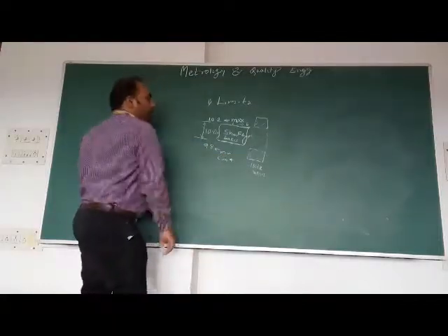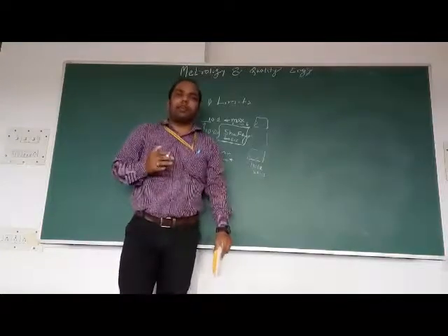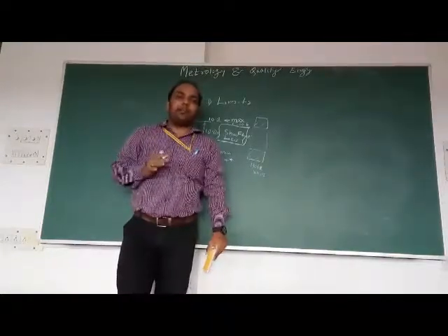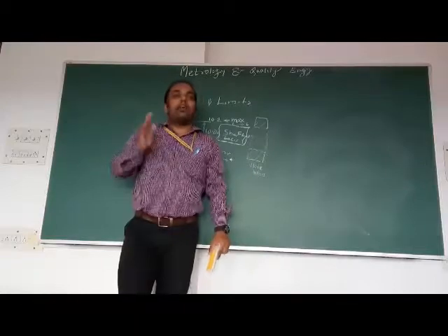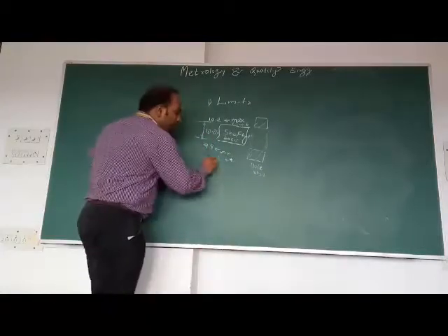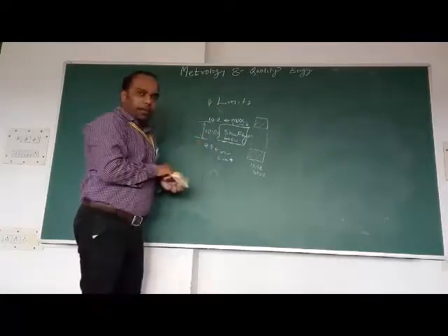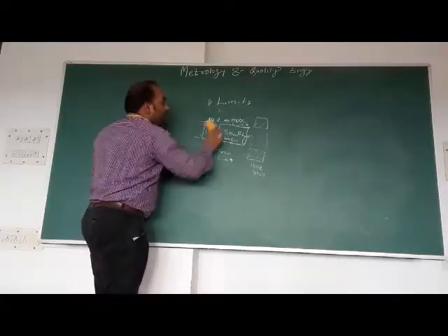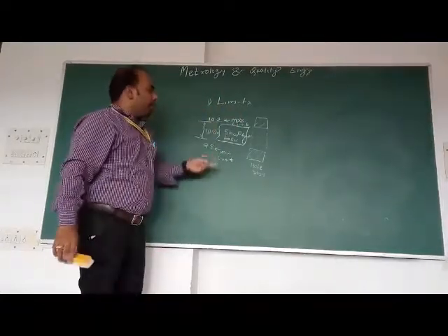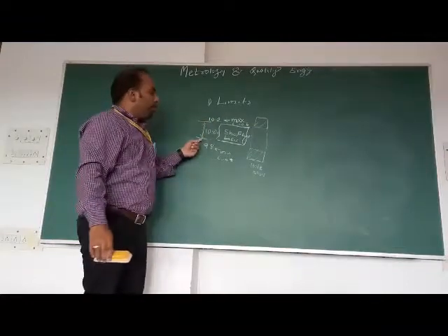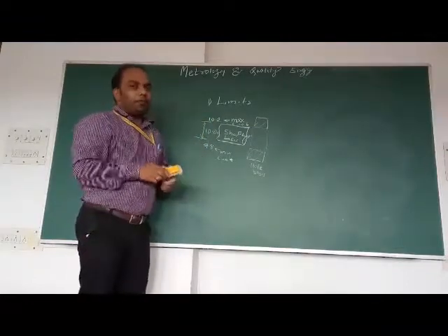Shafts made up to 10.2 cm can be accepted. Shafts made down to 9.8 cm can be accepted. But shafts below these and above these are not accepted. So the maximum limit for the shaft is 10.2 and the minimum limit for the shaft is 9.8.